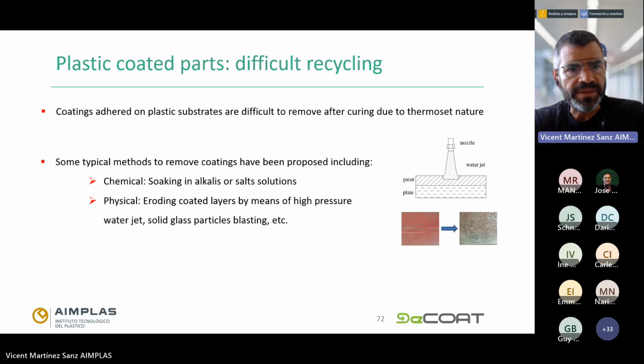Some typical methods that have been proposed in order to remove the coating layers include chemical methods, such as soaking in alkalis or salt solutions. On the other hand, physical methods erode the coated layers using high-pressure water jets or solid glass particles in order to blast and erode the outer surface of these coated parts.